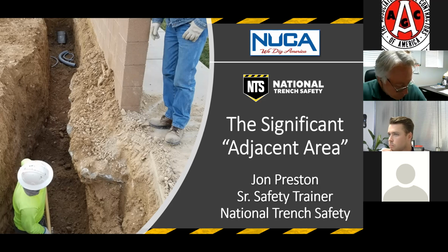You see the next question: would there be an LOI for excavations that are partially sloped along the running line of the excavation in regards to lateral shift for trench boxes? I don't know the answer to that. The LOI is referring to a letter of interpretation, and someone could always present that to OSHA and ask that question.